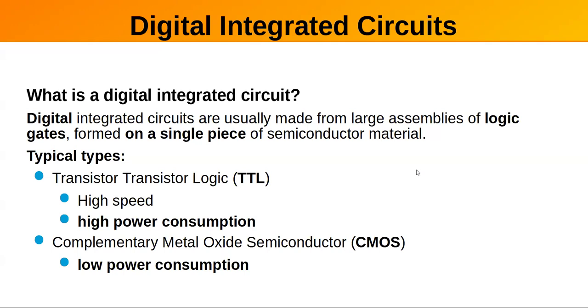TTL stands for transistor-transistor logic. It's just the way the gates were built. They're fairly high speed, high power consumption relative to CMOS. And CMOS is complementary metal oxide semiconductors. So they're using MOSFETs to build these, which is how they get the high input impedance, the low output impedance, and low power.